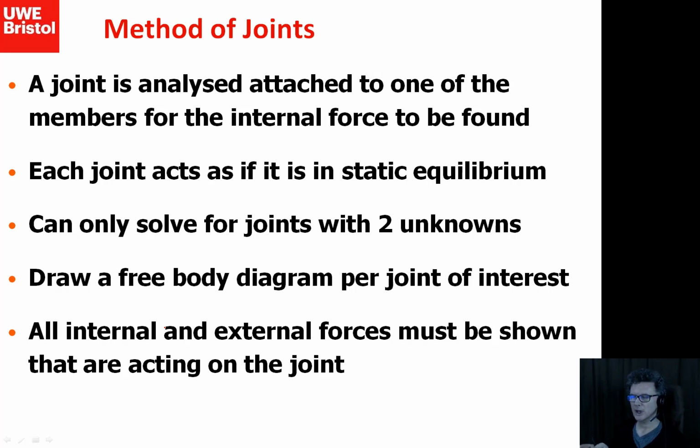Next, we're going to take a cut so that we're only going to be cutting through one member or two members. My examples here, I did cuts through one member. In actual fact, when we come to frameworks, it's always going to be cutting through two members. So we're going to choose cutting through two members. Sometimes when I'm at some point in the framework, I could go to another joint and I'd end up cutting through maybe 3 or 4 members, in which case that's probably not the joint you should be going to. You should be going to a different joint because you're introducing too many unknowns.